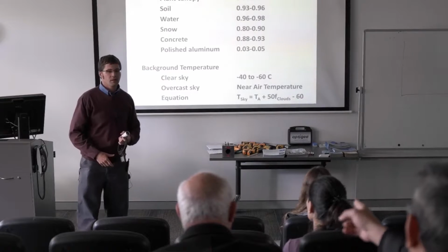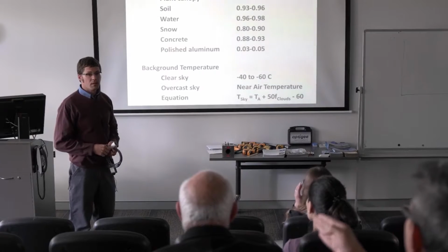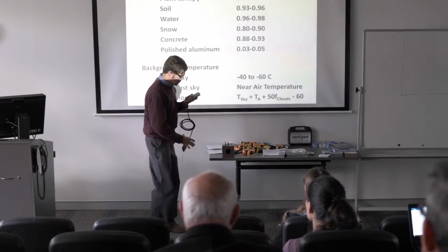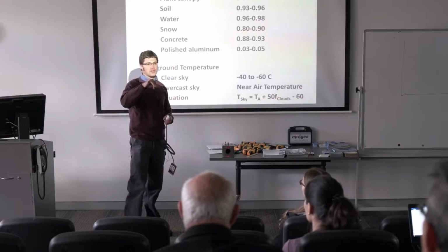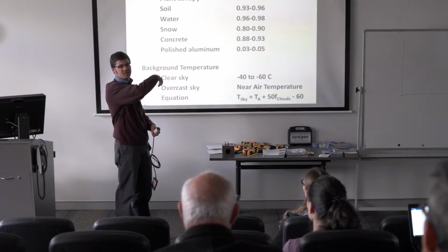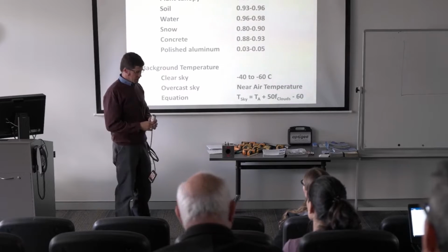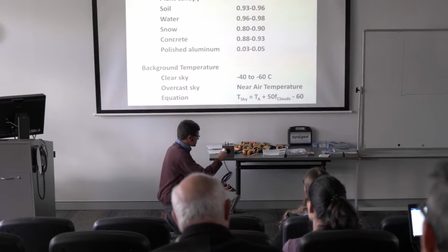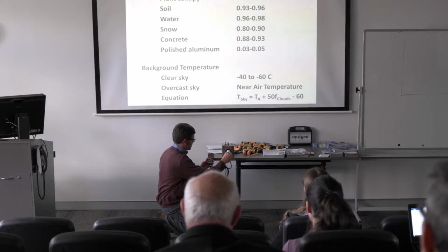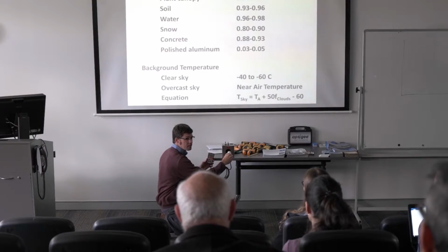What would be the result if you move a little back? If you will increase the distance? Oh, increase the distance, sure. So this is an excellent question, because you're actually jumping ahead in my slides. The next thing I'm going to talk about in my slideshow is the field of view. And so what happens is, if we put it right up next to the black body, we should measure something around 38, and again we're about 38.4. If I slowly start to move it away, in the front row, what's happening?